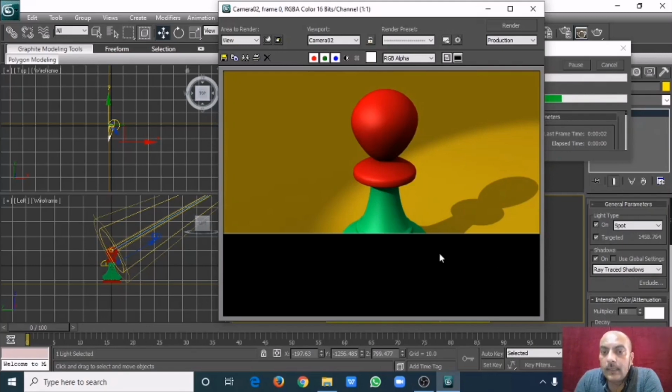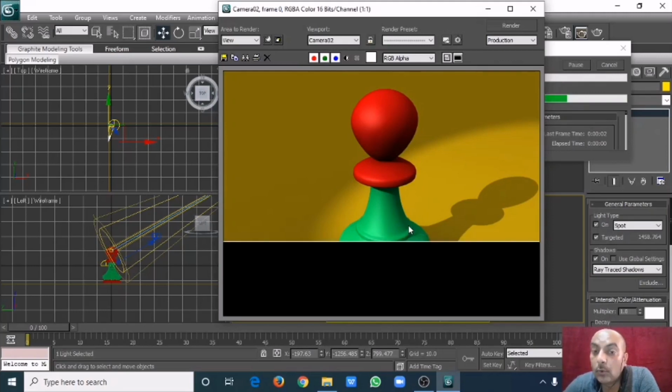And see here it is coming because of chamfer option I have used with the edge to give it hard feeling, right? Hard corner to give. So I chamfered it, divided the edge into two parts, right? Where it holds the object firmly and gives us the correct shape.